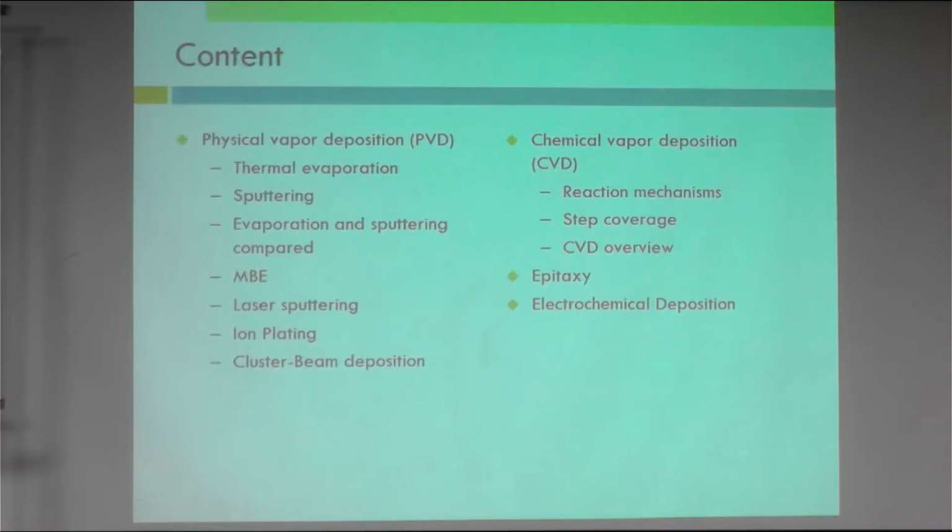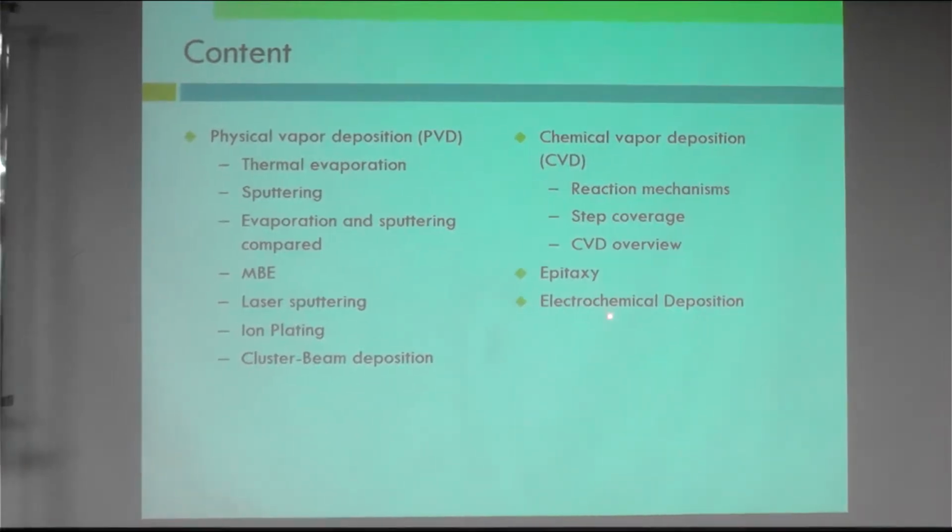So what is physical vapor deposition, or PVD? Thermal evaporation can be considered as PVD as well. We have sputtering and evaporation, and sputtering in comparison. And then MBE, laser sputtering, ion plating, and cluster beam deposition. And then we will look into CVD, chemical vapor deposition: the reaction mechanisms, step coverage, and CVD overview. Then we'll see if we have time to cover epitaxy and electrochemical deposition.